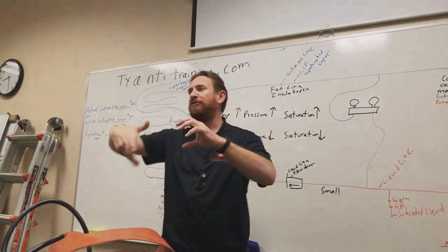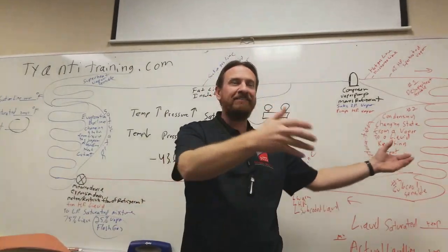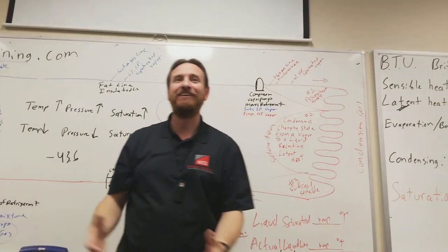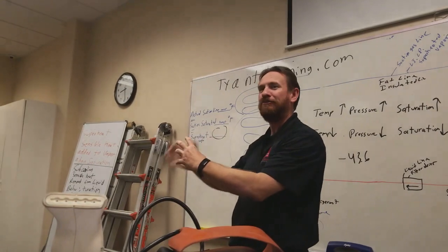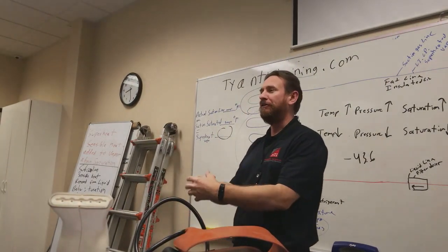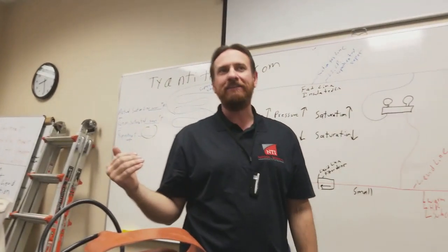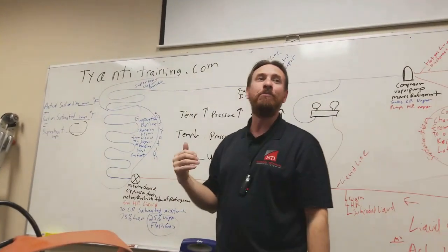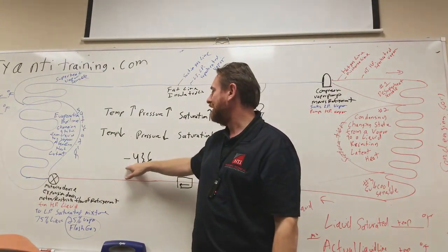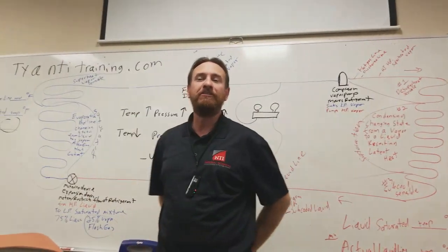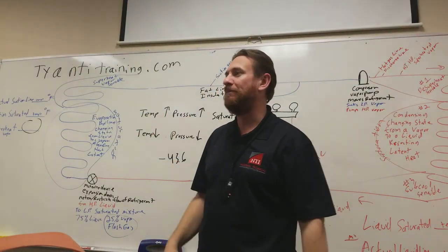And when I would unscrew that tank, and if you guys may have seen this, if you had the tanks refilled in the old days before you had a basket and a lock and you just swapped them out, you actually had to take it to a propane place, and they put a scale on it weighing the liquid, and they would have this big knob they would screw onto it, and every time they unscrew it, you would see it freeze up. Well, that's liquid propane coming out, liquid immediately boiling into a vapor. As it changed state from a liquid to vapor, it's absorbing heat, but that would be at minus 43.6 degrees Fahrenheit. So in the days of the tractor, I'd unscrew that, and there would be this little shot of propane that came out and froze stuff.